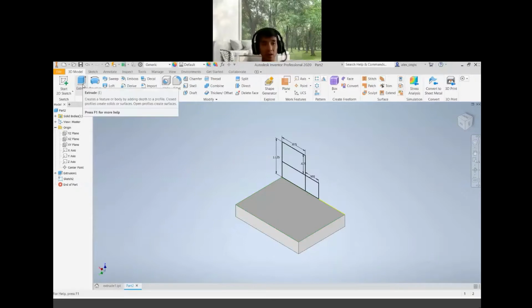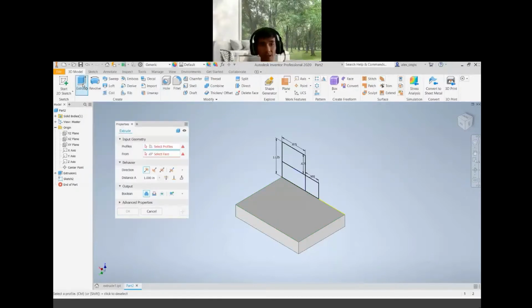So what you can do now is go to start 2D sketch. Please rotate your view so that you can sketch on this particular surface. For the first sketch, there is a default work plane. For the second, third, fourth sketch, you don't have the default work plane anymore. You need to click on the surface to select it as your work plane. So I would like you to select this one as your work plane. Click. You should have it like this. If this doesn't start from the origin and it's floating here, never mind, no problem, because the important thing is to select the right surface. In 3D it will be like this, this surface here.